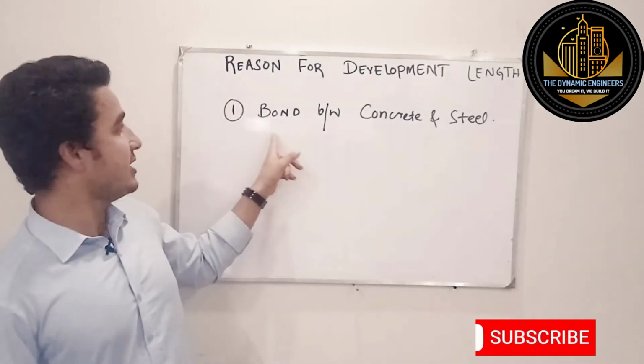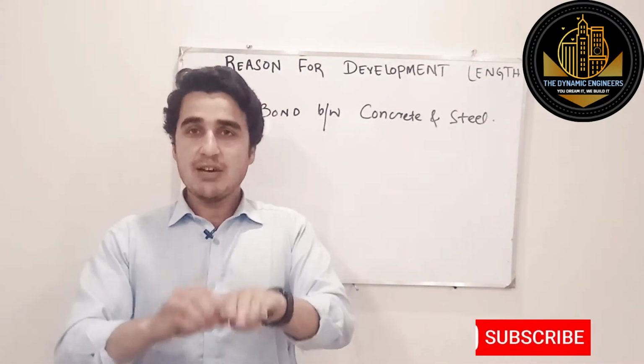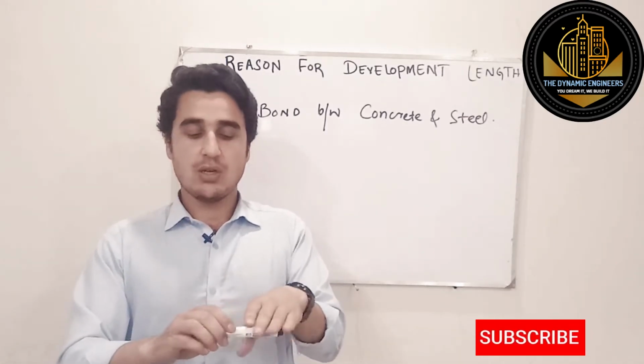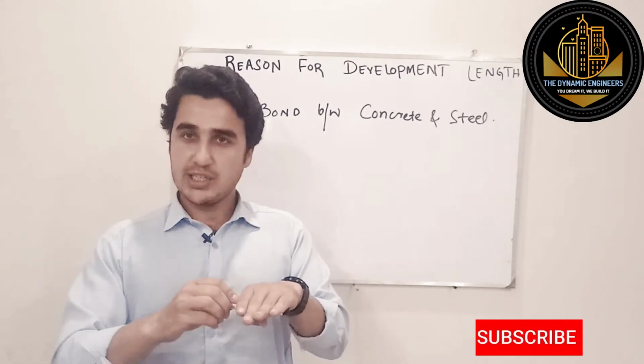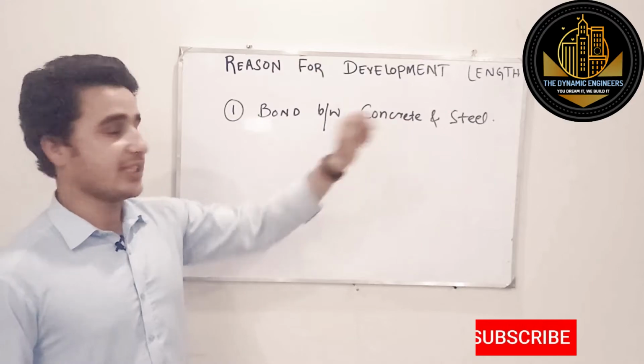So the first reason is bond between concrete and steel. If we do not provide enough development length, then there is a chance of slippage of this bar from this concrete member. So this is the first reason, the bond between concrete and steel.